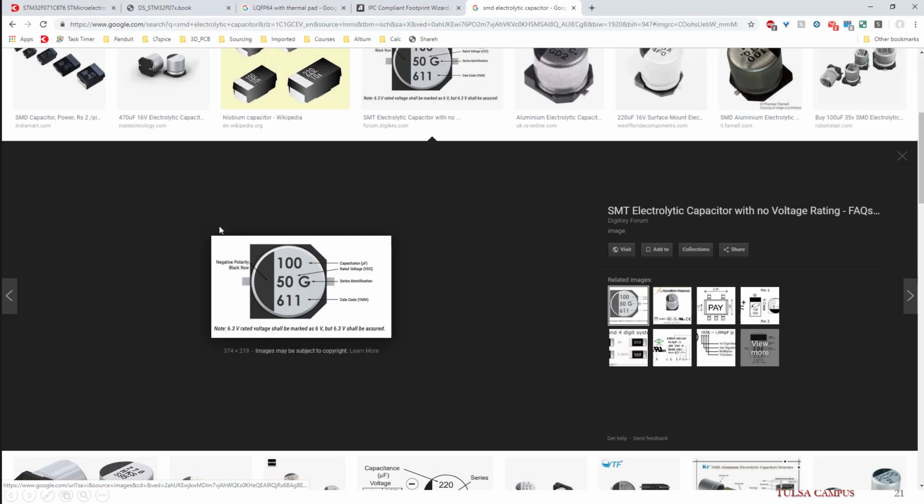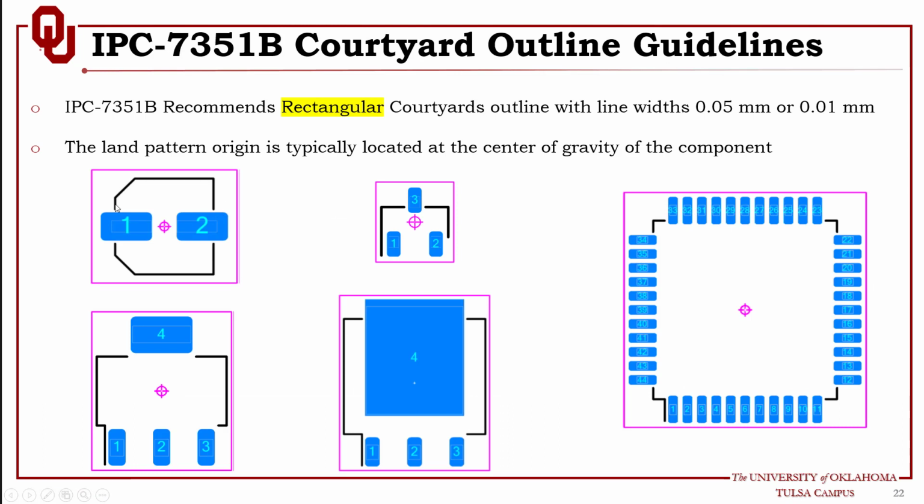So basically here it's mapping and doesn't go around the pad, as you can see in here. Also here you see it's mapping and doesn't go around the pad because this is the actual size. And look at the polarity marking in here. This is pin number 1. This is according to the standard. Polarity marking in here, pin number 1, as you can see. So the polarity marking in here is basically this shape.